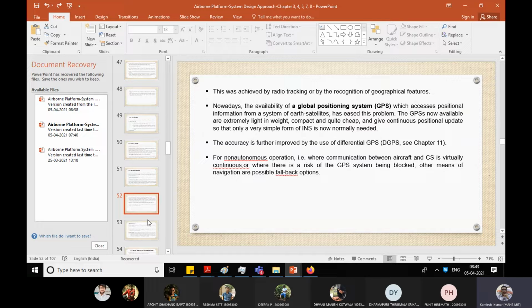So why do we need a good DOP? Just to make the information accurate. And how will you get a good DOP? When you have the maximum number of satellites detected, and they have the farthest distance. When the receiver detects at least a minimum of 4 satellites, it should pick the ones that make the maximum volume. If your receiver is one point and takes another 4 satellites spread over a very large distance, you will make a bigger volume. So DOP is inversely proportional to the volume made by the satellites and the receiver.